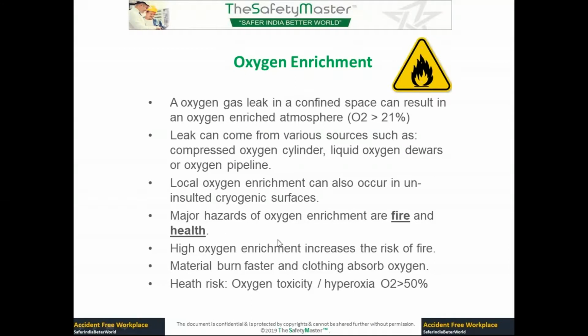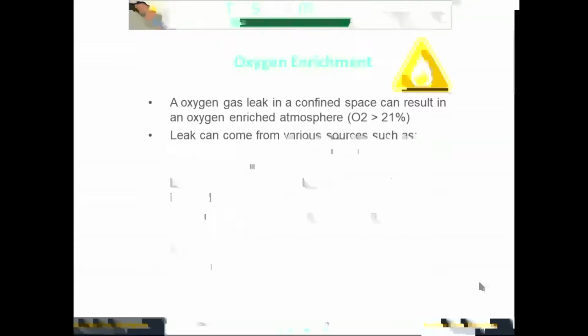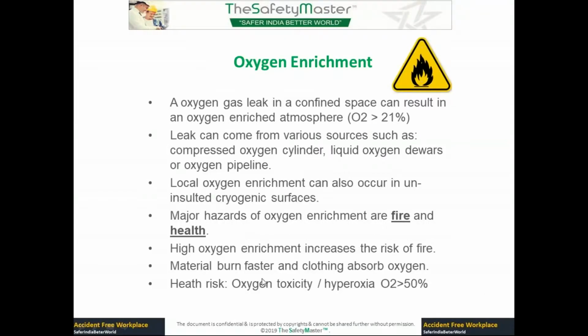And then the major hazards of oxygen enrichment are fire and health. High oxygen enrichment increases the risk of fire, material burns faster, and clothes absorb oxygen. Now take the gloves you use for handling cryogenic liquid. If you pour liquid oxygen on the gloves and light them using a matchstick, they will catch fire.